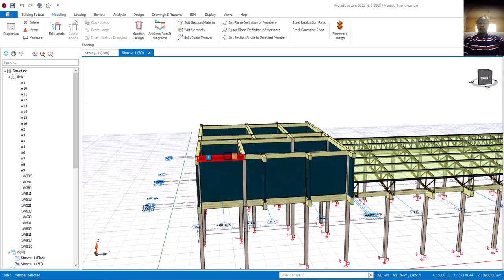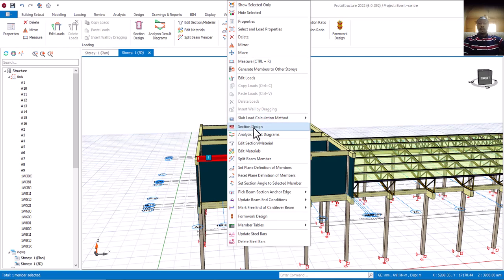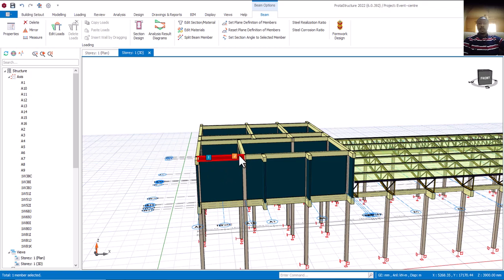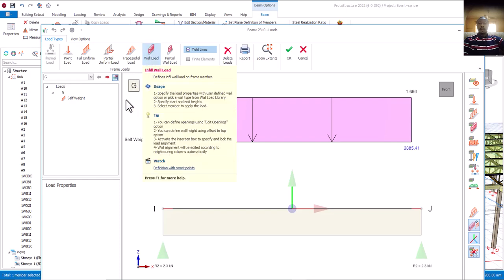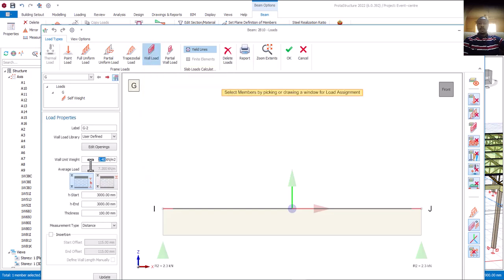You can just use block work. Let me see where the edit load is. Yes, correct. I'll come to this place now. You can just put some roof loads on it. Wall load, then 3.47. In case this is your first time and you don't know how we came about this, go and watch our part 1 or part 2, or go to Ekidel YouTube and watch some of our videos. You get it there. Now the height, a maximum of 3 since it's a small structure, let's say 3 or 2 blocks. 2 blocks, which is 400.